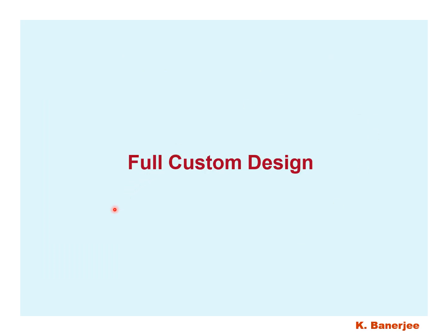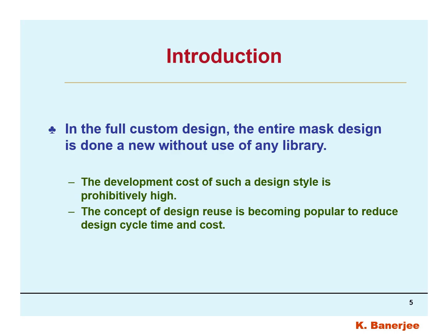So let us start with full custom design. In this full custom design, the entire mask design is done anew without use of any library. So what I am telling is that in this method the function and layout of every single transistor is customized and optimized by the designer. So a designer can craft all the circuits by hand.